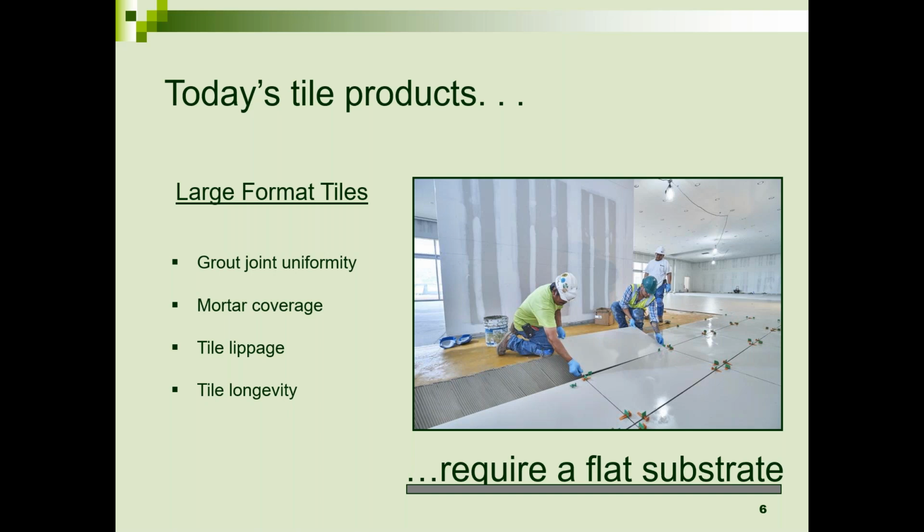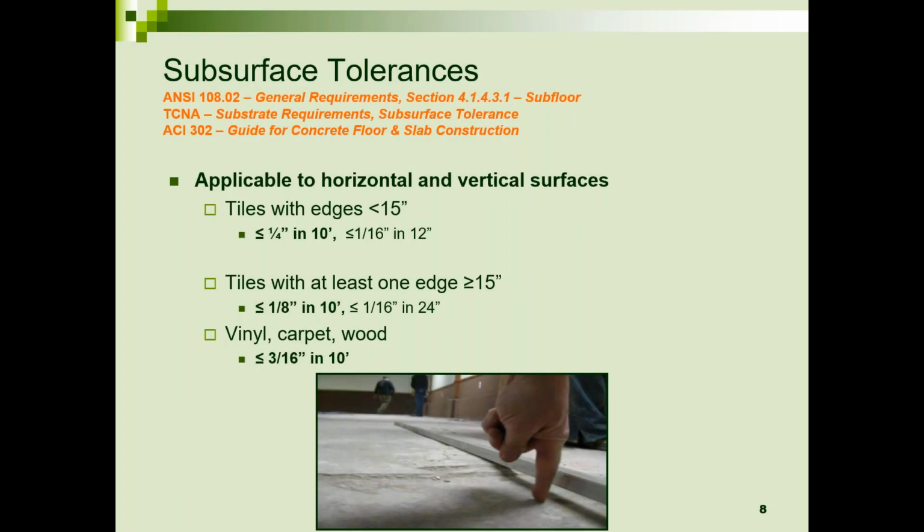Tile lippage is a physical and aesthetic issue, but could also be a trip hazard if it's installed in an area where people are moving along with walkers or canes or foot shuffling. Mortar coverage is impacted if you don't flatten the floor first. Too much or too little mortar, again, there will be problems. So surface prep is very important. There's sometimes the thought, well, I'm going to throw a membrane down, I'm going to install some mortar, and the tile is going to be installed, so I don't need to do surface prep. No one's going to notice. They will notice as that flooring system fails, and it definitely will.